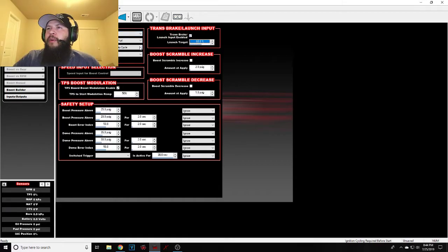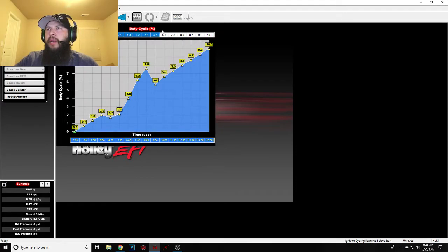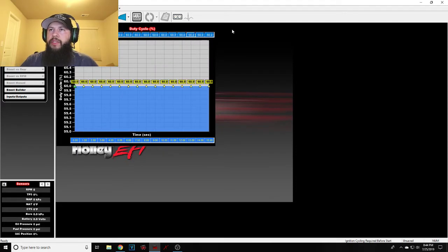So that's kind of a big one. One of the guys that was asking me questions was under the impression that that would be the same. So if you have 60% in there and it yields 5 psi on launch control, you could come in here and put 60 percent all the way across the board, and you would get that same boost all the way across.